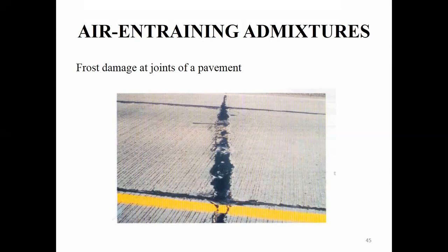And whenever water is becoming ice, what happens? You also know one more thing: the volume of ice is 10% higher than the volume of water. So the volume occupied by the water will increase by 10% when it changes into ice. So what happens? The crack may increase; the crack level will also increase. To arrest this effect, they are using air entraining admixtures. Now you may ask how this mechanism will help.